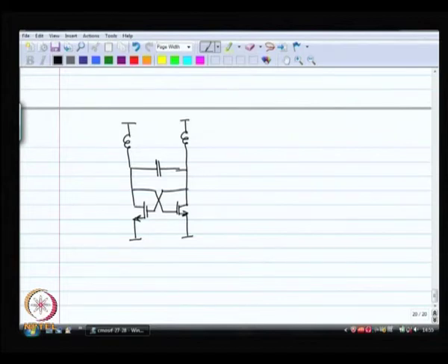Now, of course, you do not like this because there is no control over how much power this is consuming. If you look at the DC picture, this voltage is at VDD, okay, which means you have got just one NMOS as a diode between VDD and ground.